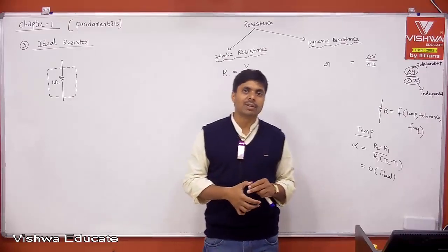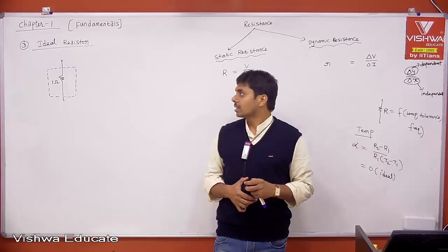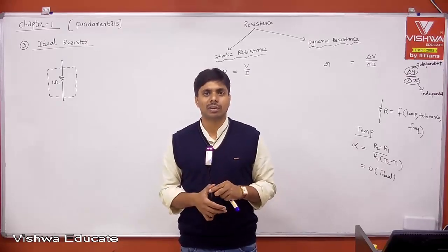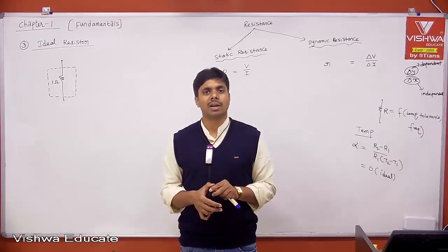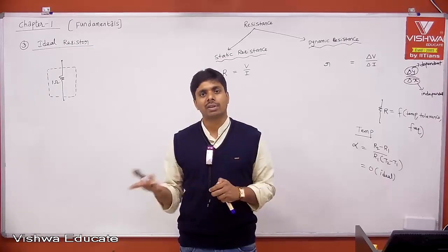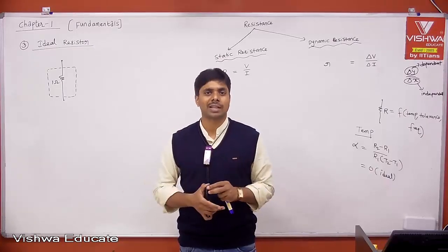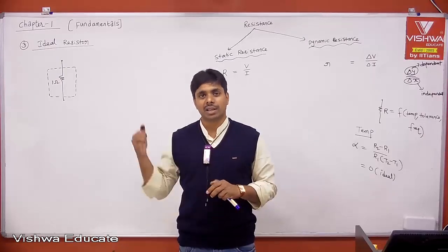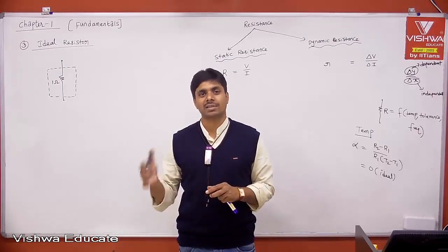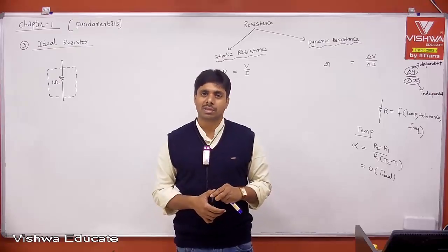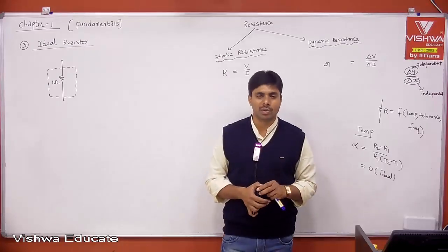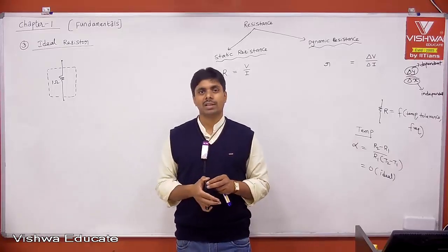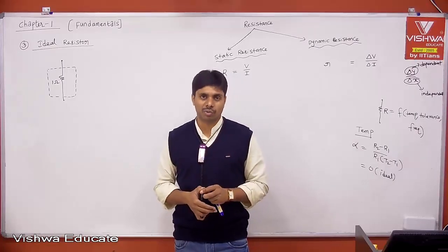But if you take your network analysis, we always take a resistor, let us say a 1 ohm resistor. We will not think that the resistor will change with respect to frequency. We will take it as it is. But if you take your capacitor and inductor, they are frequency dependent parameters. The reactance of your inductor and capacitor changes with respect to frequency, right? But in the case of a resistor, we will not take that the resistor is a function of frequency. But strictly speaking, not at low frequencies, but at very high frequencies, your resistance is a function of frequency.